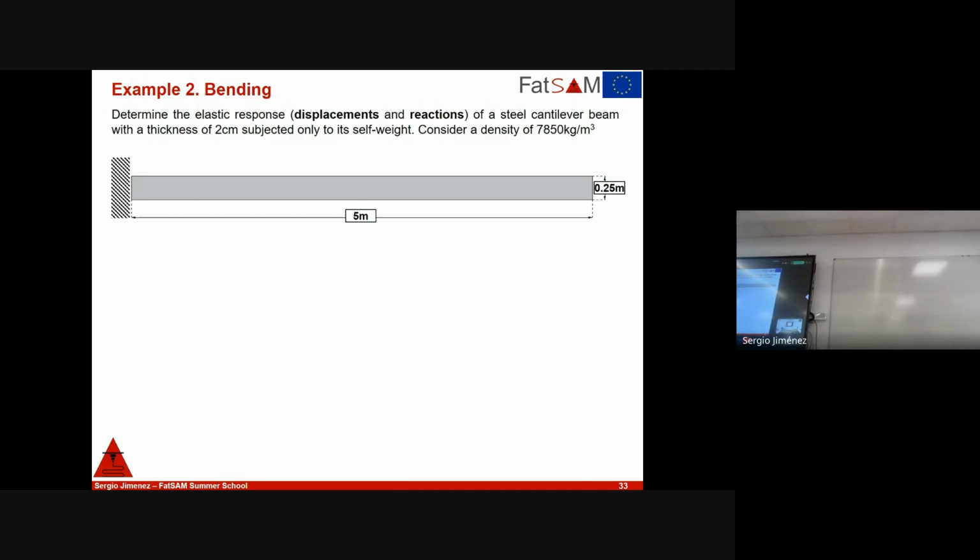The surface. In this case, the surface. If it's a 3D model, then you should create the model. In this case, it's a 2D case, you should apply it. And then click on escape or end. In this case, it's y is -1. You have this coordinate system. So basically, what it's telling you is that you will be applying a modulus, which by default is the value of the gravity, which then will be multiplied by the density that you are specifying. It's done automatically.